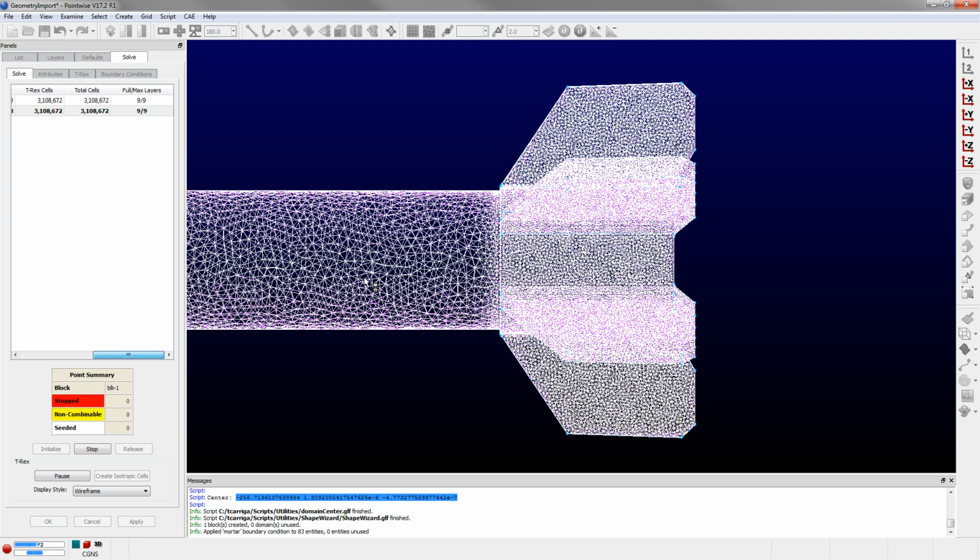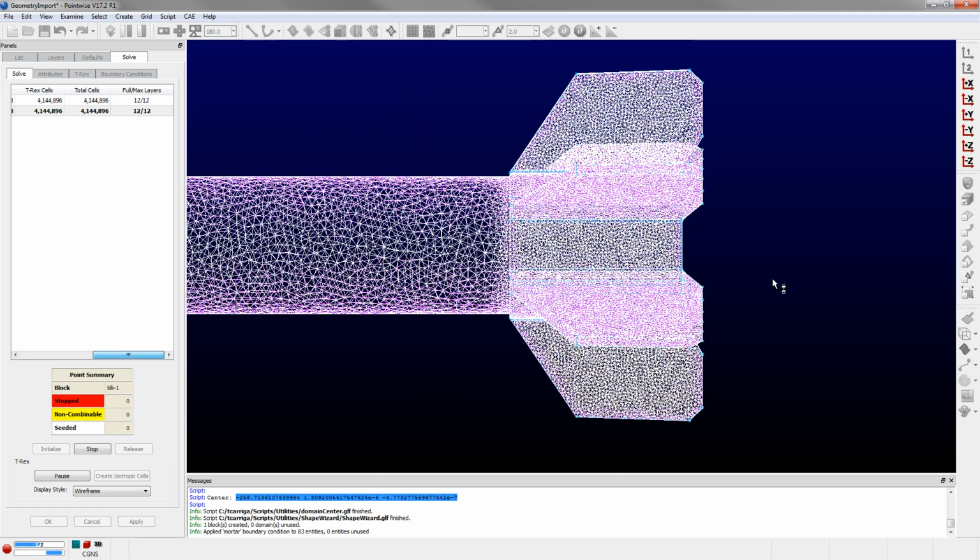It's not turning red because of poor quality, it's turning red because it's reached another stopping criteria, mainly the fact that the elements have reached an isotropic state. Because at the end of the extrusion, this front is going to be passed off to an isotet mesher, and then the remainder of the volume is going to be filled. So you can actually see the extrusion taking place.